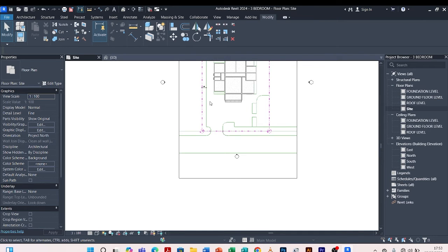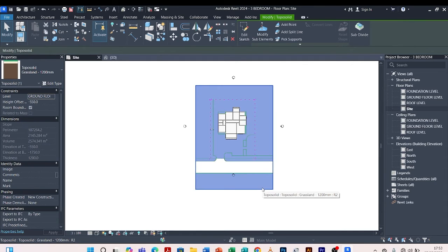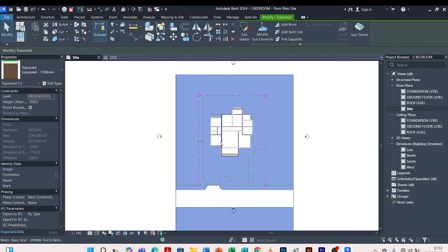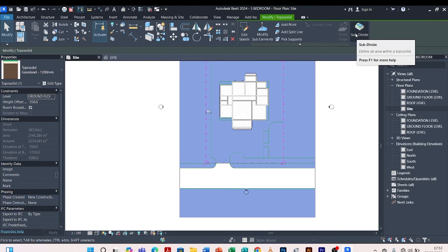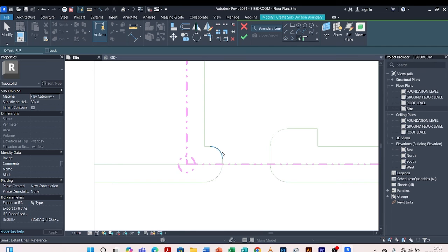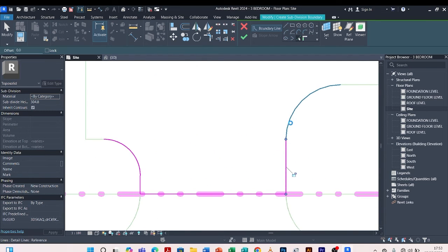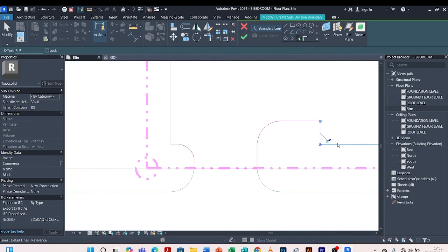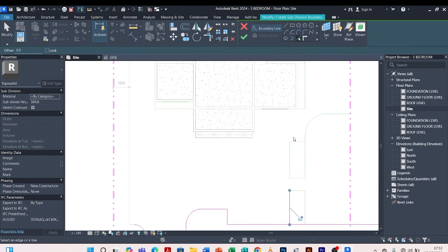You come back to our site plan. You click on the topo solid. What next are we doing? Let us create the paved area. Come here, click on subdivide. We are going to pick lines again. You come on pick line, pick this line, pick this, pick this, pick this. You pick all the way as the pavements or the paved area is moving.